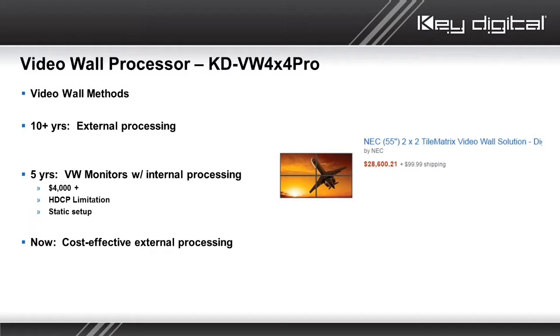Now, in order to achieve the video wall setup that you need for your configuration, they're not just 2x2, they might be 3x3, for example. You have to let each monitor know its configuration and its address, if you will. Every monitor is different how they do this, but usually you plug in a computer with some software into the service ports of said monitors.